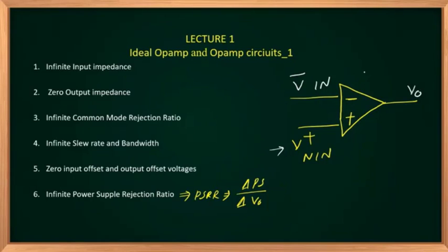Along with this, sometimes you will represent the positive supply rail and negative supply rail voltages. To ensure a symmetrical swing, we usually select the same magnitude for positive as well as negative supplies. Nothing wrong if you are connecting 0 volts or a ground signal to your negative rail.